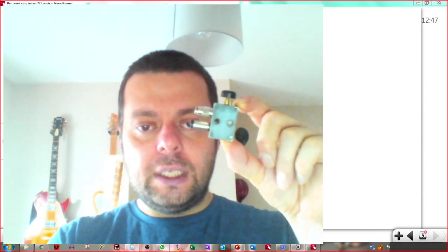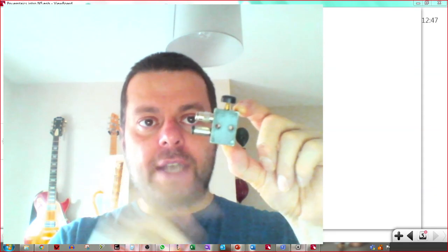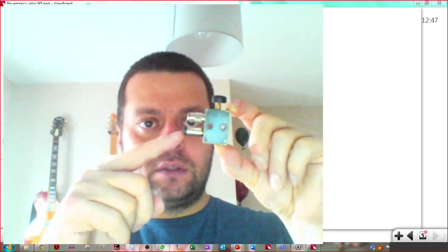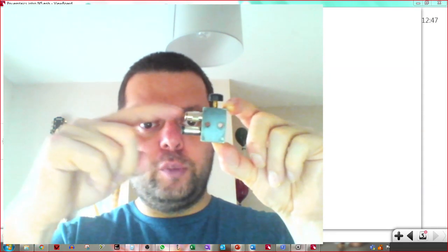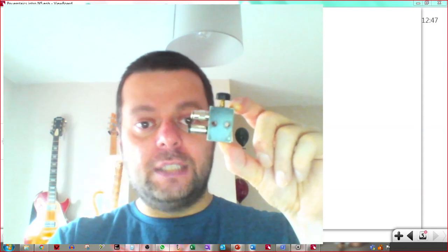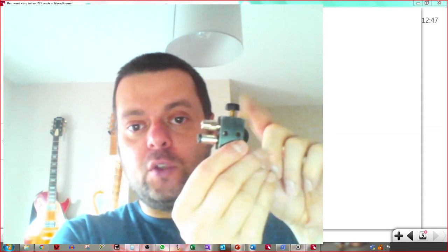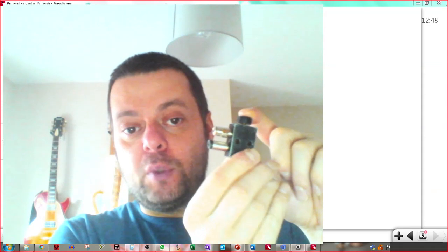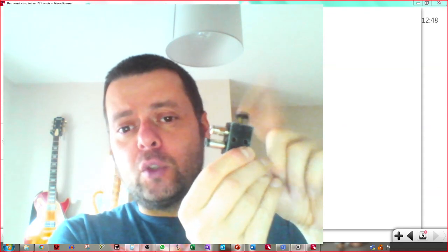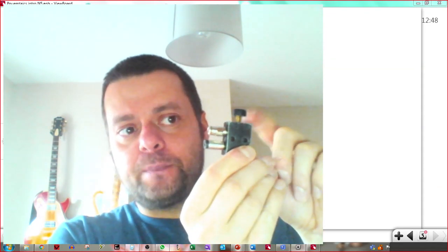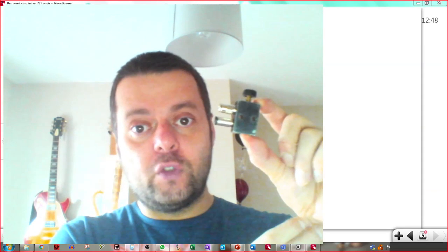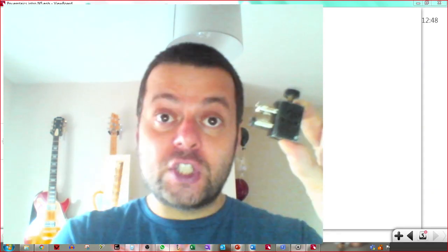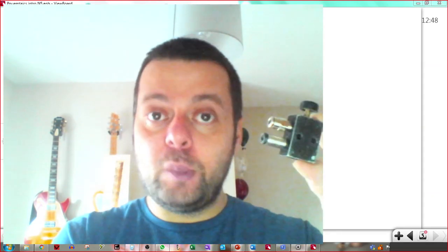So, yeah, that's the input port there, and that's the output port there. And this is a push button spring return 3-2 valve. I push that button, that's me connecting the input to the output, and if I let the button go, the spring pushes it back up and disconnects them. That's a 3-2 valve push button spring return. I would like you to sketch that one and label it as well, please.